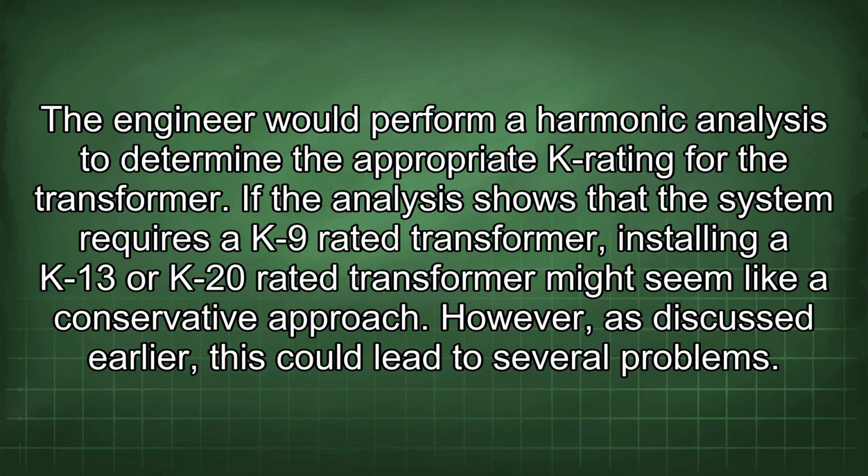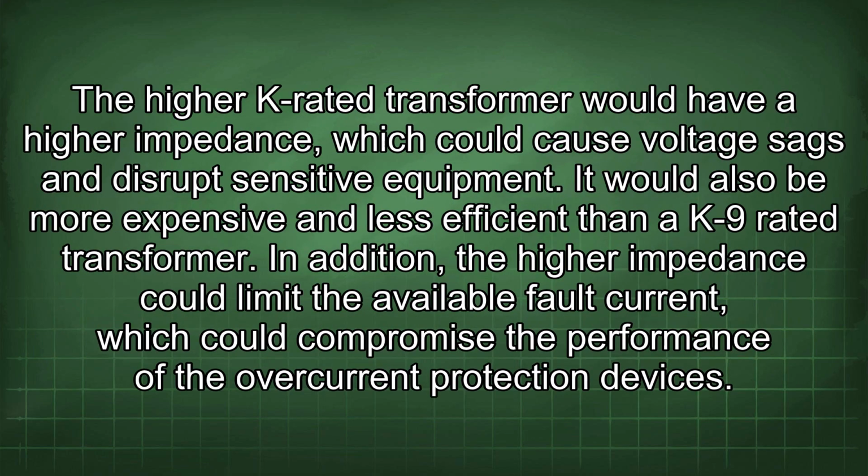If the analysis shows that the system requires a K-9 rated transformer, installing a K-13 or K-20 rated transformer might seem like a conservative approach. However, as discussed earlier, this could lead to several problems. The higher K-rated transformer would have a higher impedance, which could cause voltage sags and disrupt sensitive equipment. It would also be more expensive and less efficient than a K-9 rated transformer.